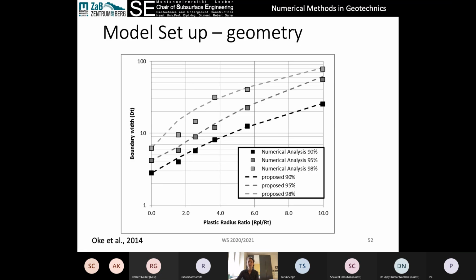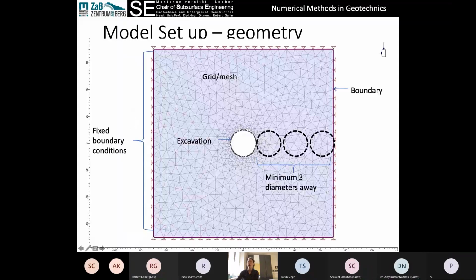The reason that we have to do that is if we come back and look at this model here, oftentimes weird things are happening with the stresses, especially at the model boundaries. The reason is that there's a mathematical solution to the stresses in this element, and there's no way for the stresses and the displacements on these nodes to be shared in this direction.